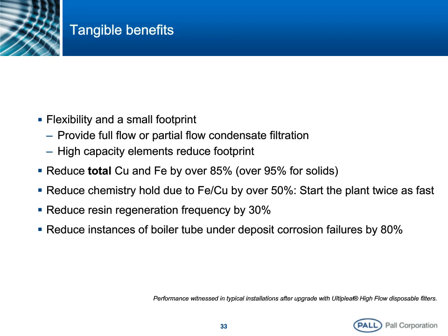And finally, as I mentioned, you get to reduce blowdown. Because you clean the water, you lower the cycle of concentration, and you tend to reduce blowdown at least by 50%. So the quantity of water that you currently are dropping in the boiler blowdown, basically cut that in half. Again, conservative number.